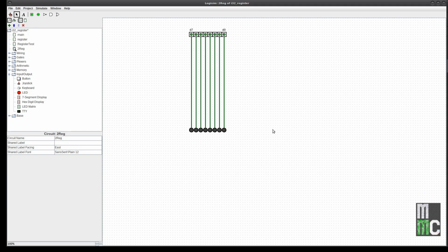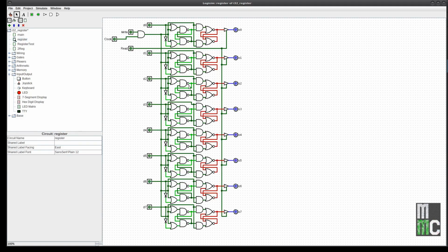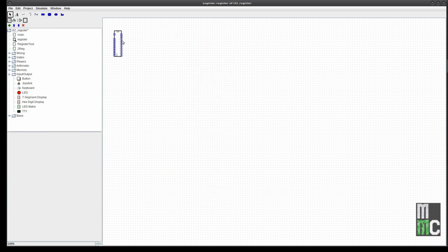Okay, there's our 8-bit bus with an output down here. When I go to simulate mode, you can see that the LEDs will come on no matter what I put on the bus. Now, as you recall, to get a register, we simply click here and drag over to here, and here's our register. This is the external representation of this circuit. Remember, we go here, and there's what it looks like, with all of our pins labeled.